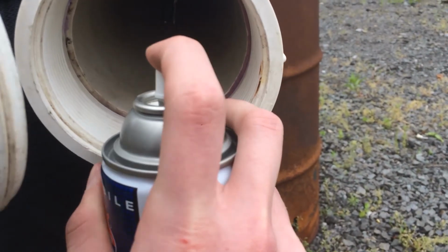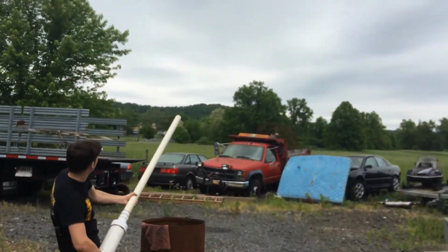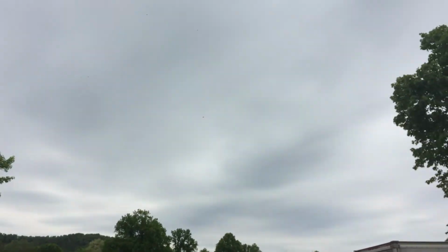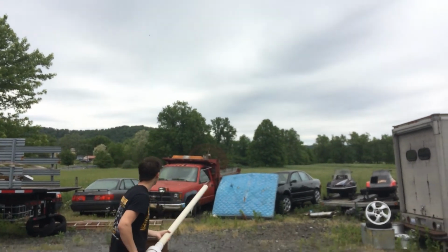The largest source of error was that we were not able to measure the velocity of the projectile at the muzzle, and instead we had to rely on the average velocity over distance. Because of this, it can be assumed that the actual muzzle energy of the cannon is somewhere in the neighborhood of 100 joules. Another source of error related to being unable to measure the velocity at the muzzle is drag.